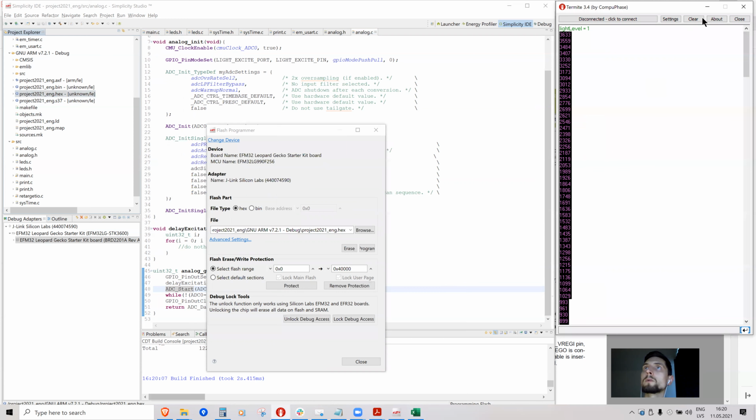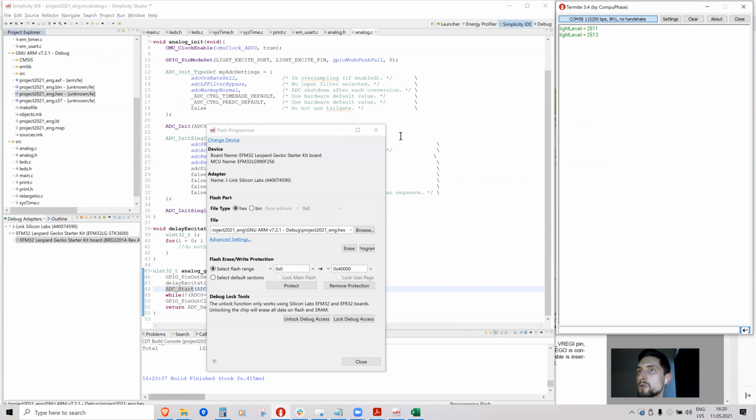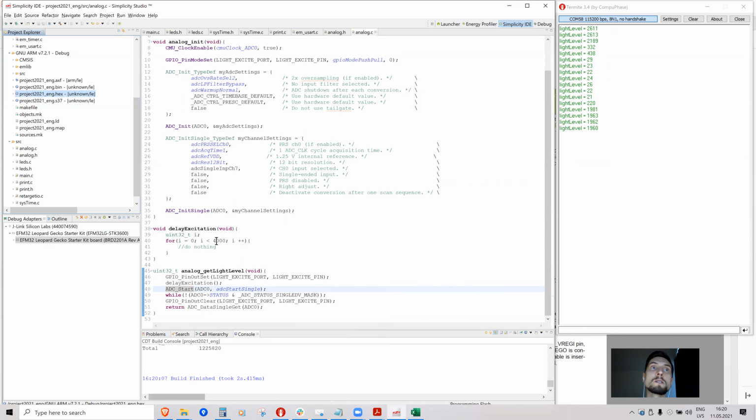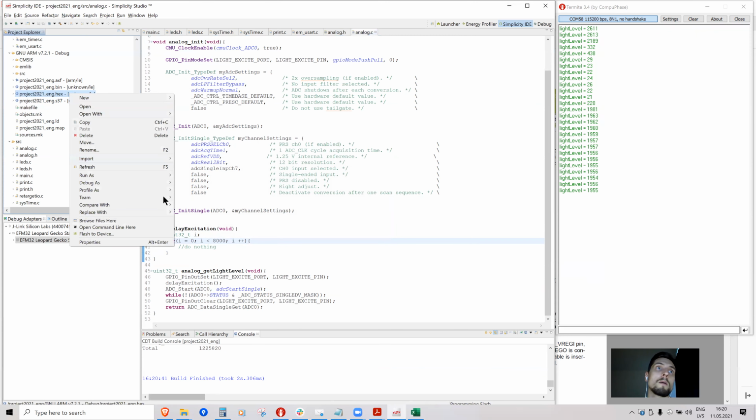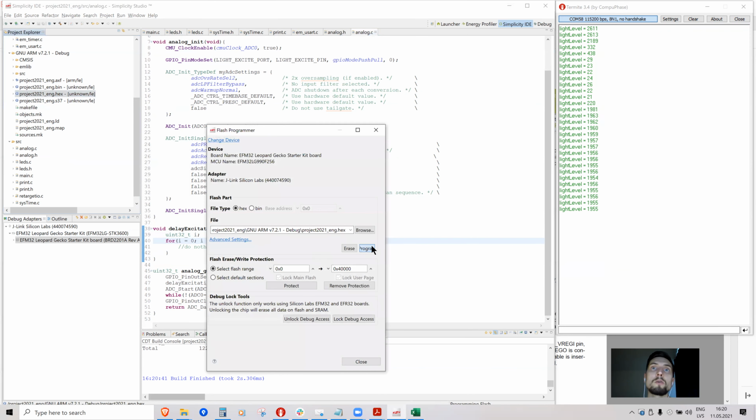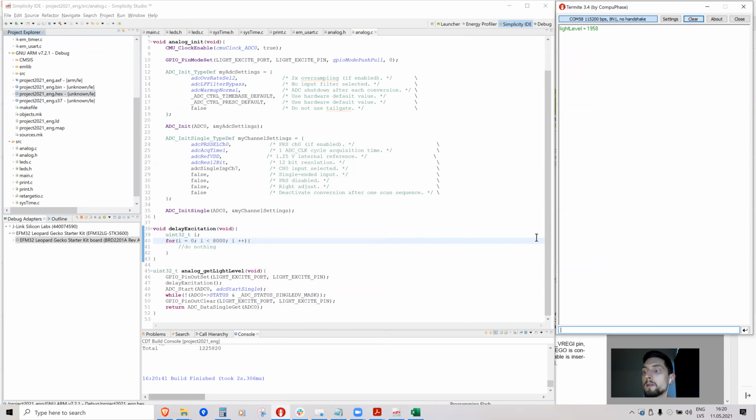And let's look at the output. So when I put the finger in front of this sensor, it says 29. Previously, it was something like 9. So it's still a bit too long time, too short time. What I can do is I can double the time from 4,000 to 8,000. And you might say that it's a very big increase, but I can keep a lot of intermediate values this way and actually get the result faster.